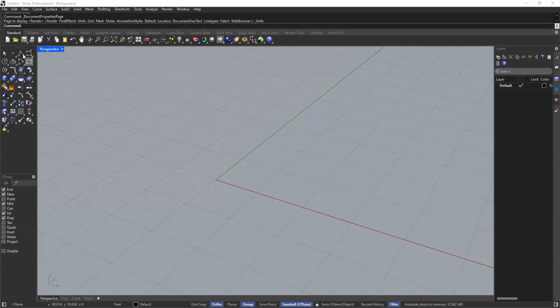So I'm going to start off by drawing a line. Okay. So I'm going to go over here and use a polyline. I'm going to right click. Notice a little pull down that pops out. I have polyline and line segment, and it has a mouse next to it. That's letting me know that if I click on this button using the left click, it's going to give me a polyline. If I use this button and right click, then it's going to create a line segment. Now, I am not going to spend all of this time explaining the difference on every single command. If you're interested, remember that you have the help button over here, and you could click on either one and learn what the difference is.